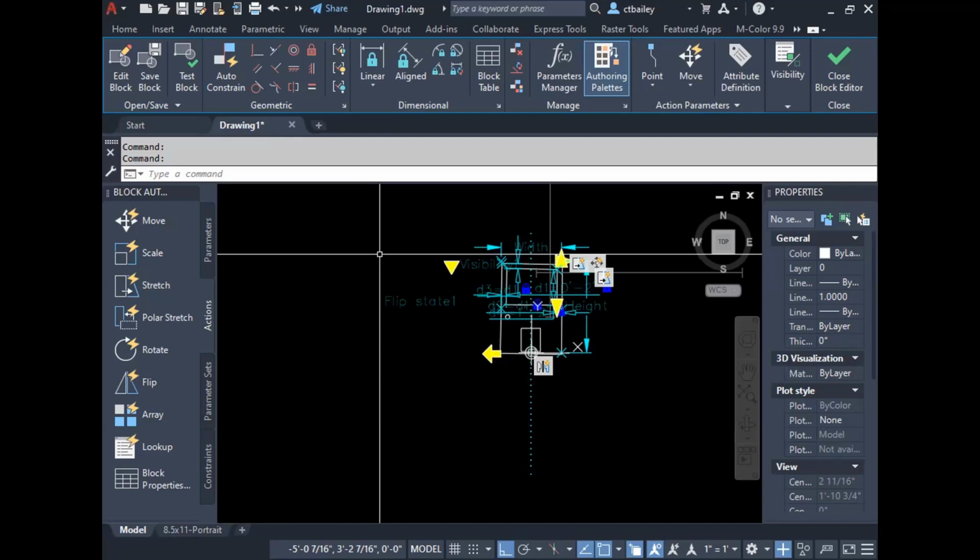Take your phone, get right down on it, put the controller on the table, take your phone exactly perpendicular to it and shoot it. Also, put a stick of wood on top of the thing to give you the full thickness. Then you can use a construction layer, build a box, 4 inches wide and 1.5 inches tall, and keep your work inside that box. Take a shot of the thing with your camera, email yourself that picture, and then insert it as an XREF into AutoCAD.